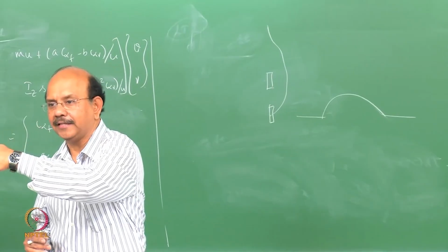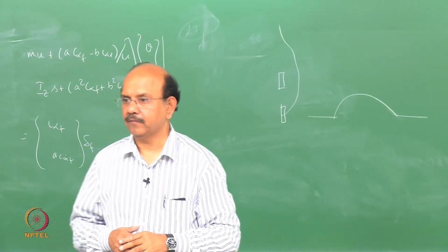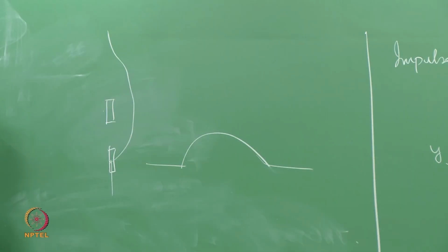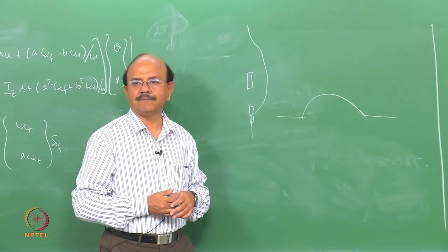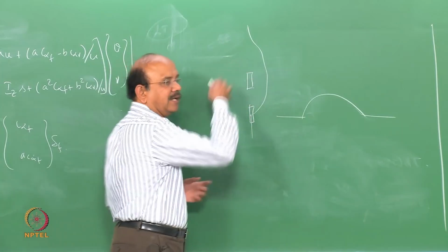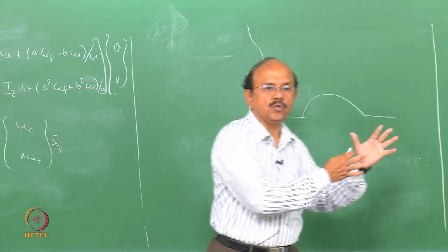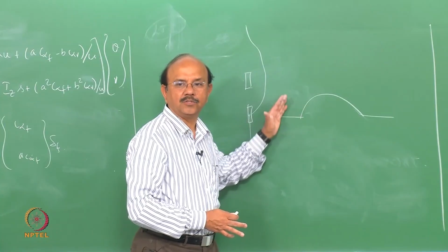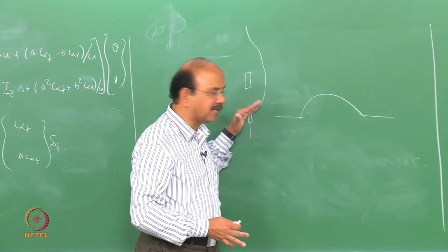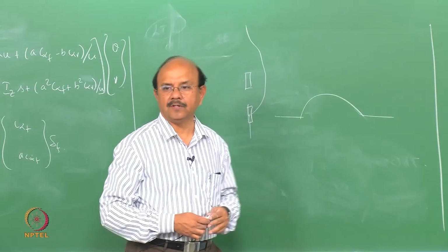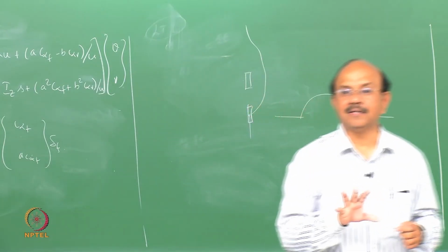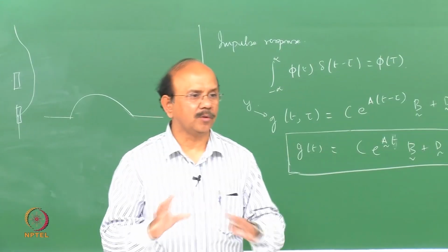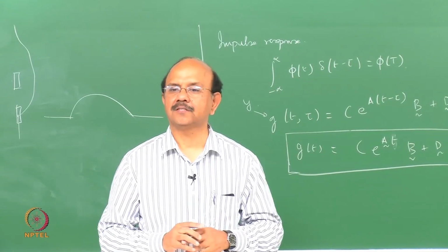Is the vehicle following that? That's what becomes important. Here, more than the yaw, it is the lateral acceleration that becomes important, because you do not want to go off the path. This may be done at higher speeds, and so the lateral acceleration as you take that curve becomes important. Yaw is not that important. It's not that they are not important, both of them are important, but the relative importance will be different in each of these cases.